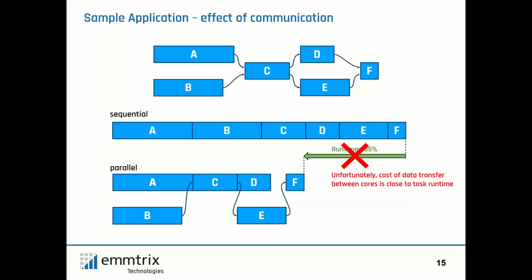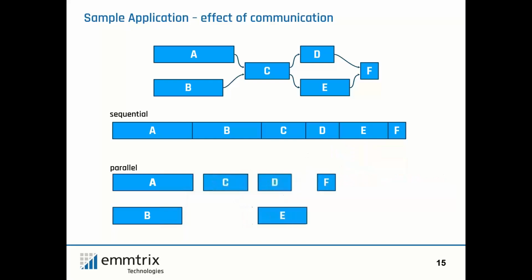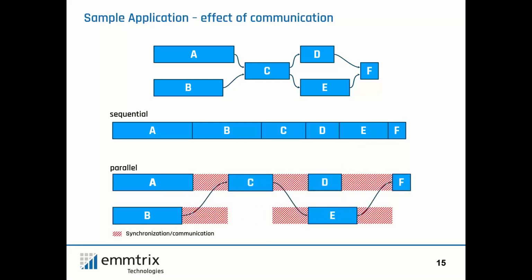But unfortunately, if we don't take the cost of data transfer into account, which is pretty important in control applications where tasks are short and every data transfer or synchronization between cores will add a lot to the runtime, you will not achieve the runtime reduction you want. The synchronization and communication overhead might be significant, and you might even get a runtime that is higher than the sequential case.